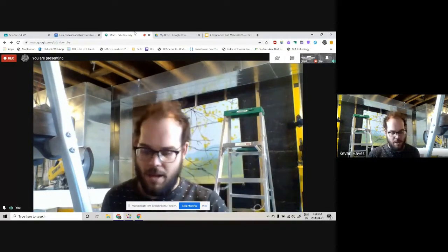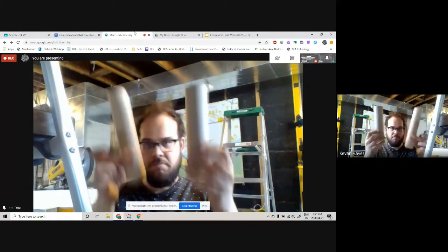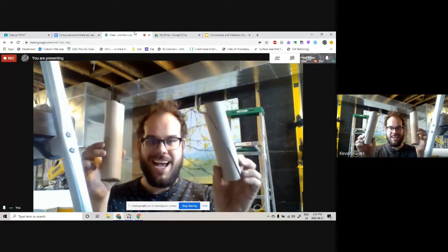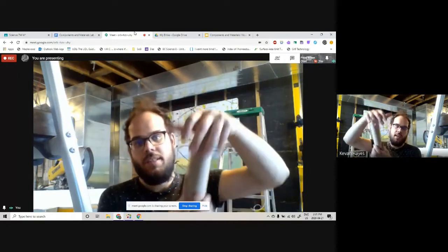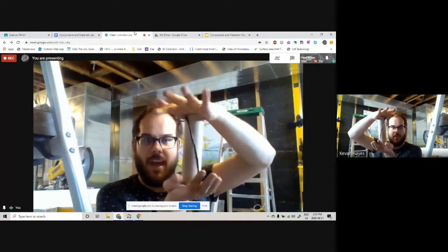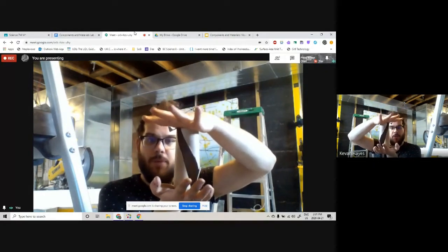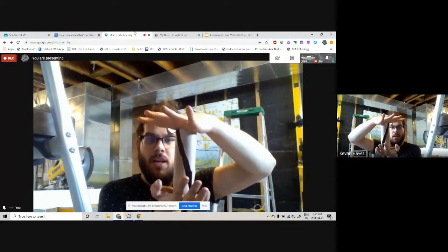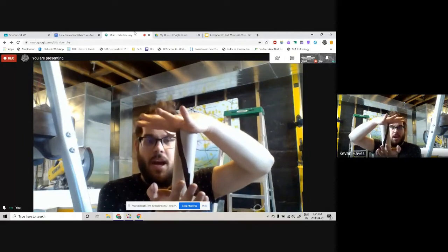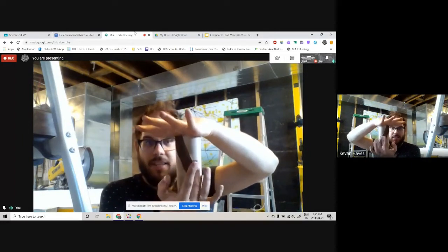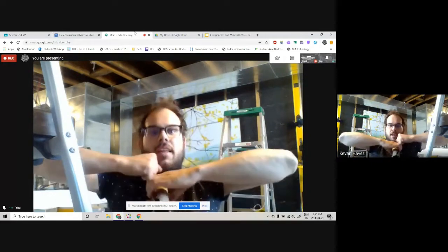Why? Well, if you get a second piece of material, exact same kind of material, but for this one, put a cut in it. So cut up one side. And what you'll notice now is if I take this and I apply forces to it in the exact same way, you can very easily start to see how this structure fails. Notice that by trying to compress this tube, the cardboard wants to pull itself apart. It wants to kind of get fatter. And to do that, it needs to have these pieces move away from each other. So you notice for them to move away from each other, they're experiencing tension.